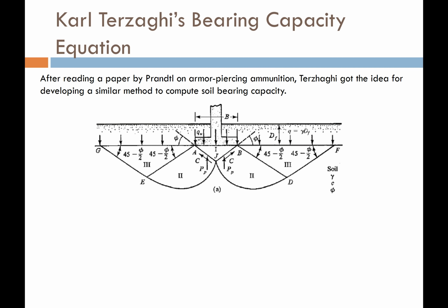It's really quite fascinating. So here I have my foundation. It's buried at some depth, D sub f, and it has a uniform load of q sub u. And if we load this foundation up, we're going to see a couple of things happening. First of all, I have an elastic zone. This is a zone directly beneath my footing, and it develops in the shape of a wedge, or like a pyramid. As the footing goes down, this soil gets trapped and becomes kind of like a snow plow or a blade, part of the footing itself, and helps drive the soil beneath it out of the way.